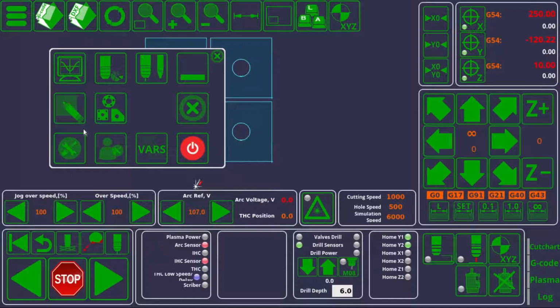So you'd have, let's say, a servo motor that would be on when you're starting up the application, and it would automatically turn off when you close the myCNC program. Additionally, this will also cover the creation of the manual servo on and servo off commands. For example, let's say the user is operating the machine and they would like to toggle the servo motor status.